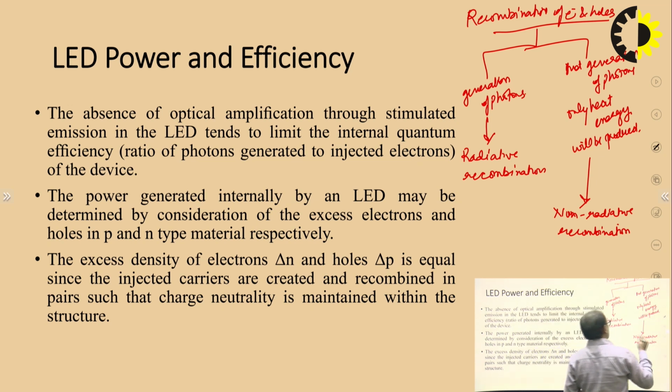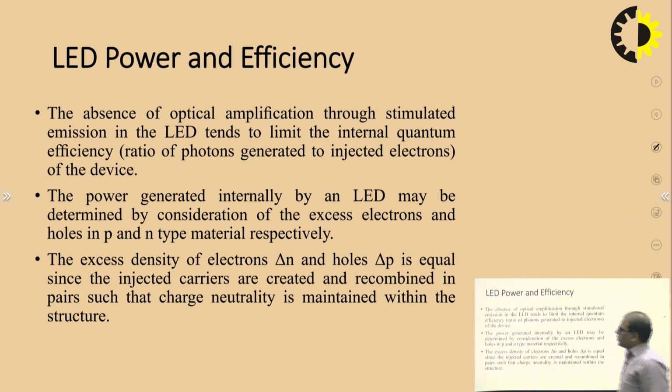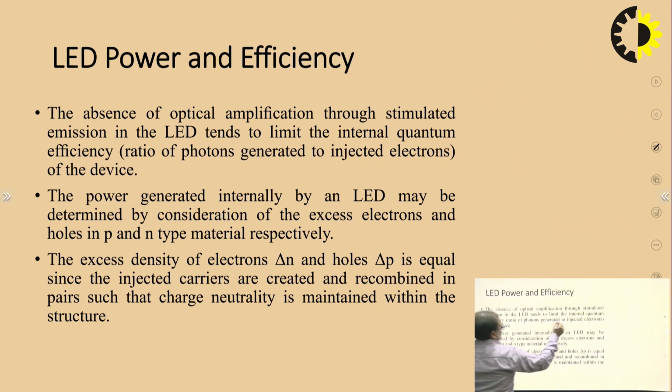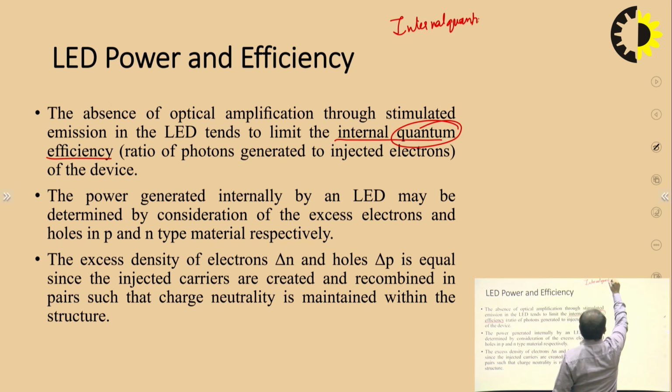Clear? Now I'll start with the efficiency of LED. This is the basic prerequisite which you should know. First one is the internal quantum efficiency. Quantum means we talk in terms of photons and electrons. This internal quantum efficiency will be equal to output by input.